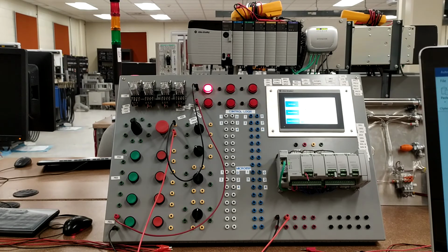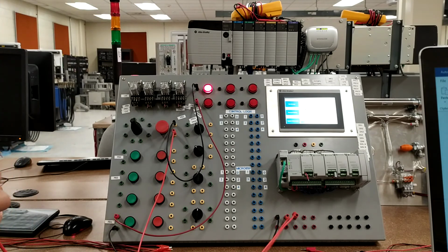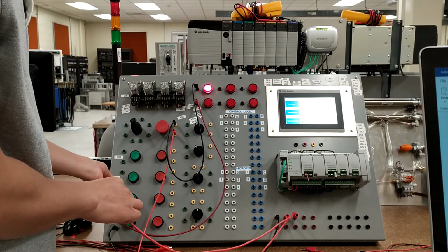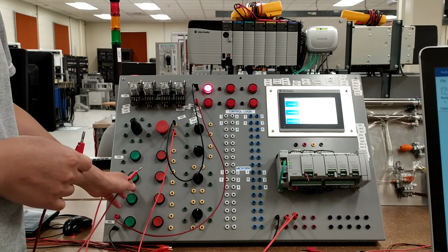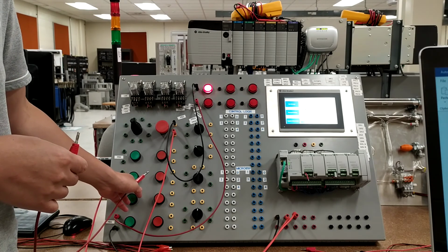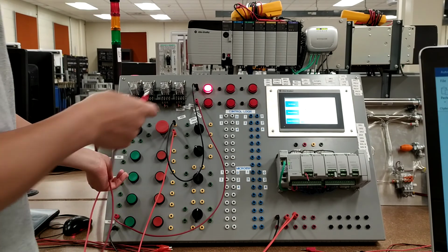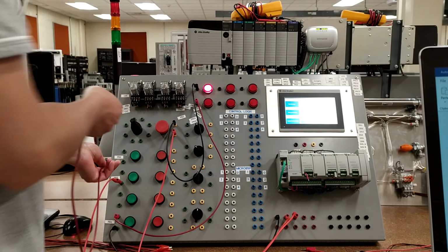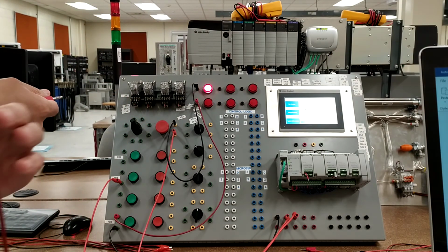First, we start from the power supply and connect to PB3. You need to remember which terminal is connected to the power. You cannot connect it directly to the pilot or the other push buttons, and you cannot connect the positive to the common, because this will generate a short circuit.